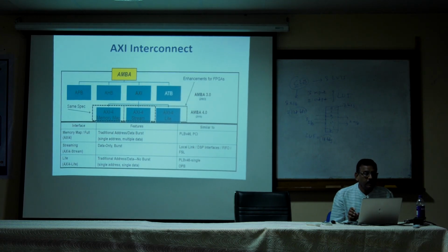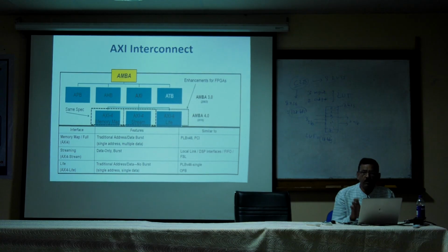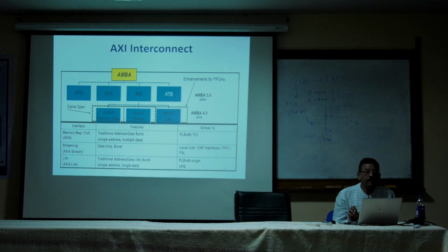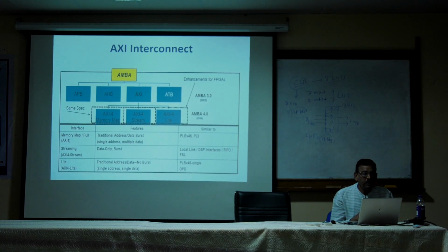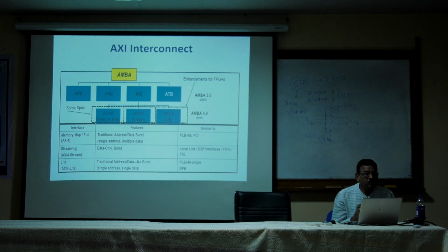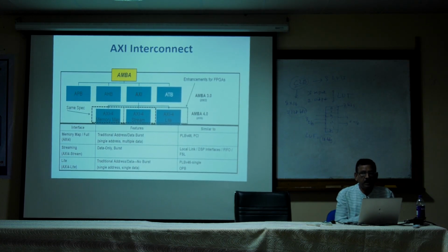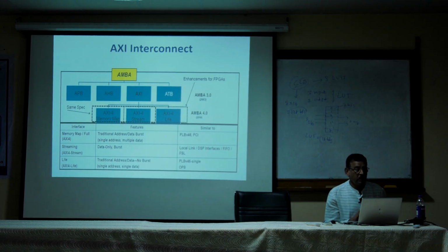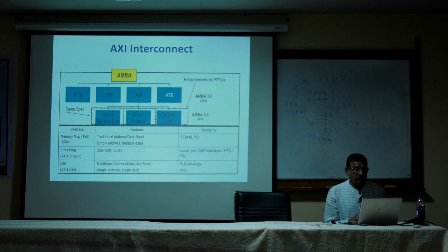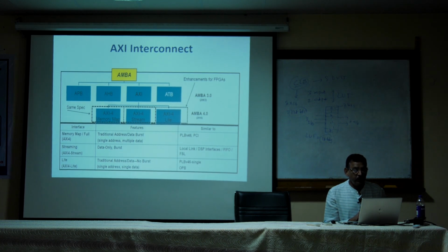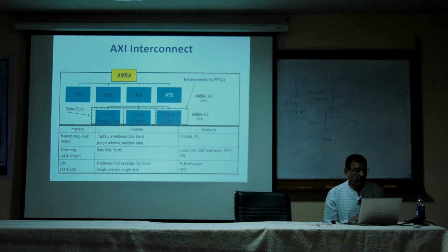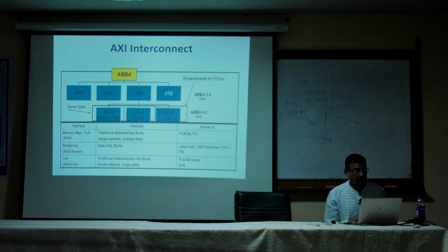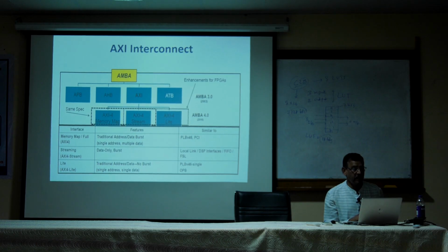Streaming. AXI4 stream is one more subcategory of AXI4. This is data only, there is no address, continuous transmission of the data, streaming. Data only and burst, like DSP interface, FIFO, FSL, local link. So streaming is data only, or burst transfers also we can use.